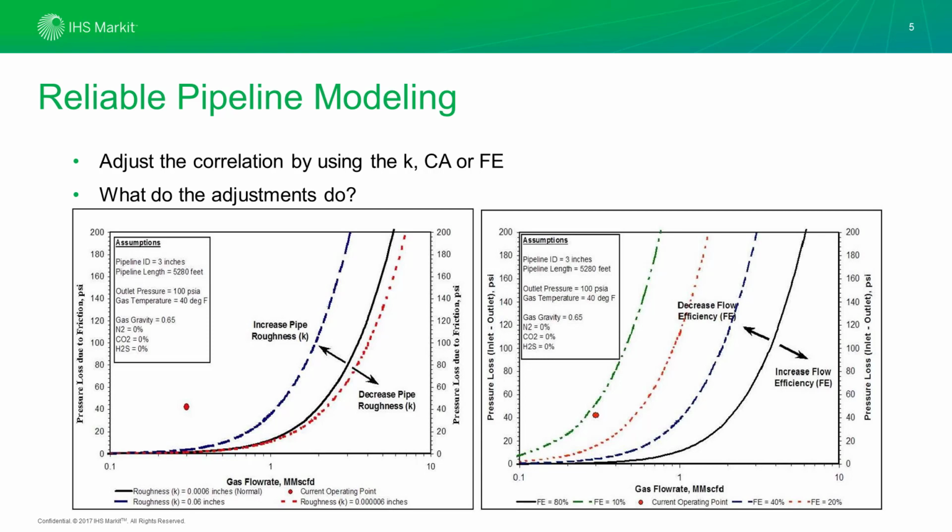However, in situations in which we have liquids that are going to be gathering in low spots due to low gas velocities, what we could see is that it wouldn't reflect the changing conditions adequately, because with the hydrostatic pressure loss or with liquids sitting in those low spots, it's not going to adjust a whole lot. You're not going to have the same additional pressure drop when you're going to be increasing your flow rate.